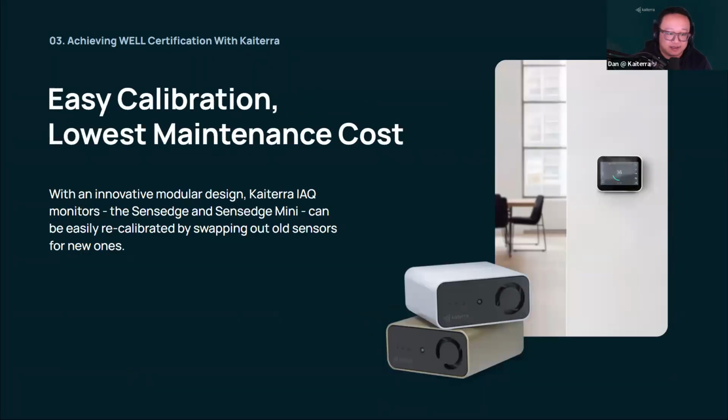Now, calibration is a very important part of air quality monitoring. You want to make sure that your sensors are all measuring accurately. And while all air quality monitors should be calibrated prior to their initial installation, how these monitors get recalibrated will vary. The traditional way of recalibration typically requires either having someone come in and manually calibrate every monitor in your building, which can take up a significant amount of time and coordination, or having someone uninstall the monitors, ship them back to the manufacturer, have them recalibrate the sensors, ship them back to the building, and have them all reinstalled.